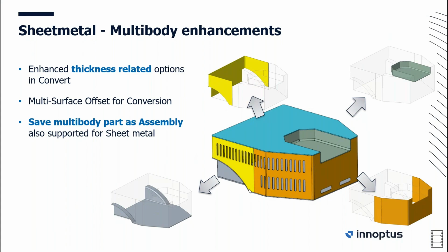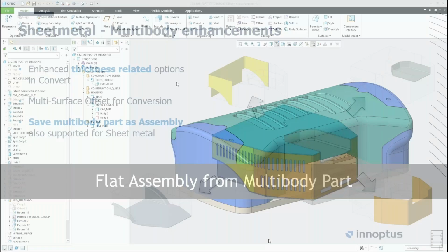We select surfaces with a thickness, so every individual sheet metal part has its own properties, has its own thickness, can have the thickness to the inner or outer side, where you can very quickly make that connection through those parts. And in the end, of course, you need to export it to a solid, an assembly. That's the power. Let's have a look at that first step.